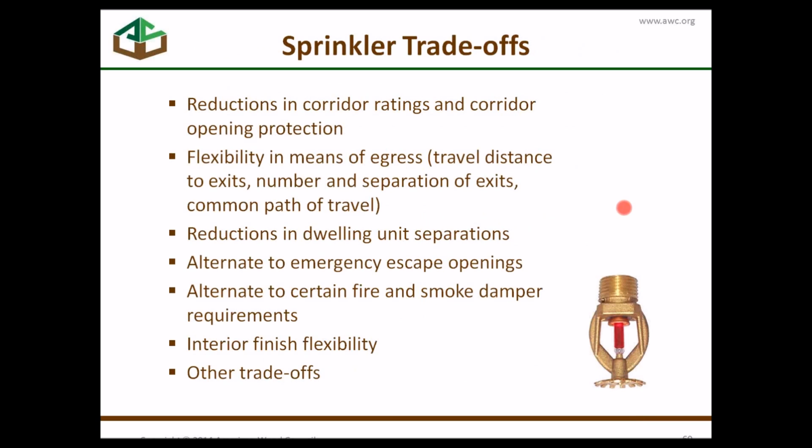Because number 2 here says if it's located more than 3 stories above grade plane, your Group M has to have sprinklers. So don't be caught by neglecting to look at the Chapter 9 limits, the sprinkler thresholds there.